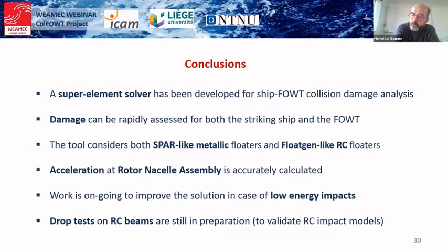Work package 2 of the project is still in preparation, where we will perform some drop tests with rigid and deformable semi-spheres against reinforced concrete beams, in order to validate our super elements involving reinforced concrete behavior laws.